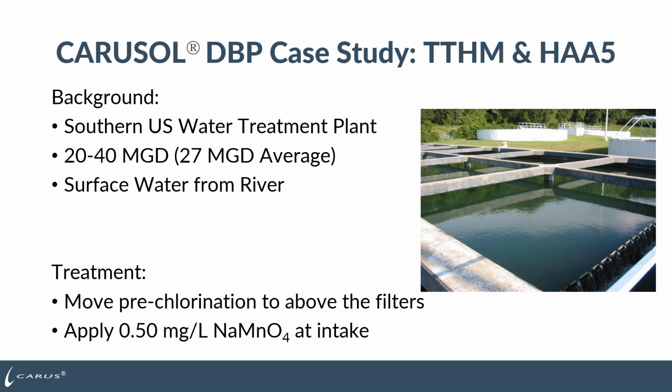Their treatment was, they wanted to move pre-chlorination to above the filters. So they were going to move it from the front of the plant to the back of the plant. And they wanted something that was easy to apply at the intake. Now, this plant was directly on the river, so we didn't gain much contact time, but they did have a river pump station, so it was just easy to add the product at that point.